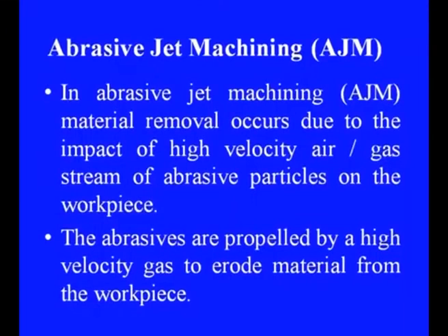In abrasive jet machining, material removal occurs due to the impact of a high velocity air or gas stream of abrasive particles on the workpiece. The abrasives are propelled by a high velocity gas to erode material from the workpiece.